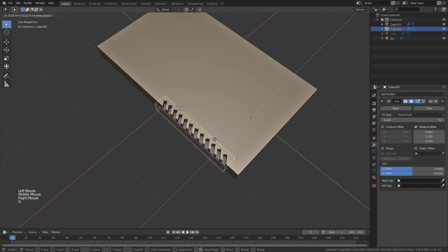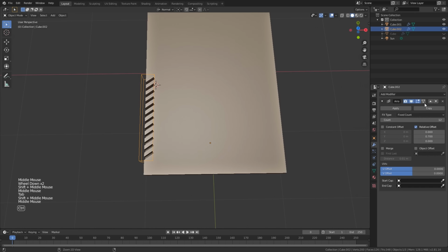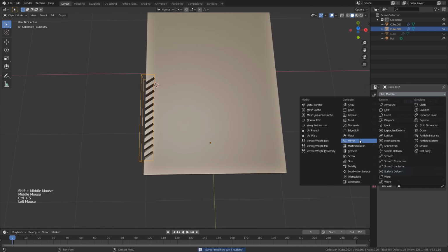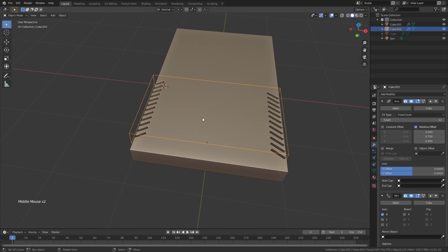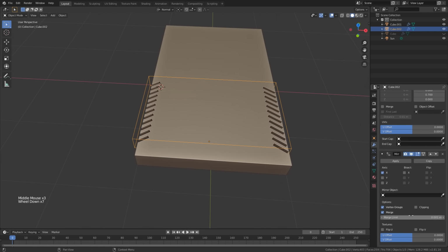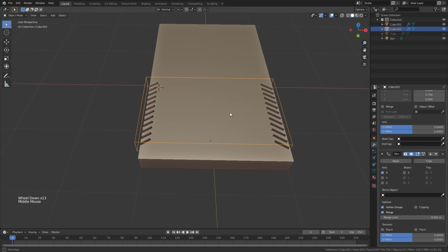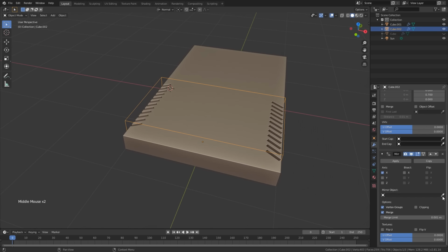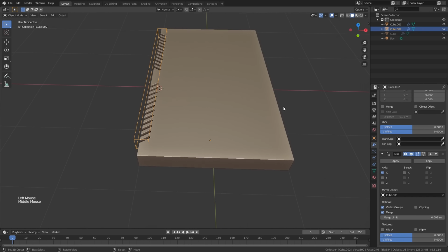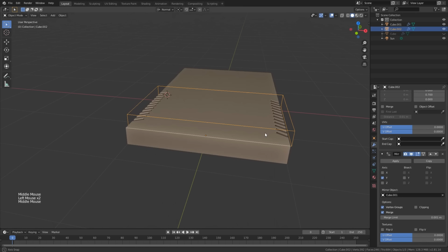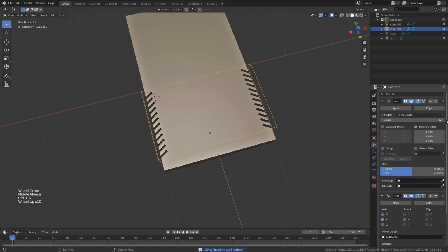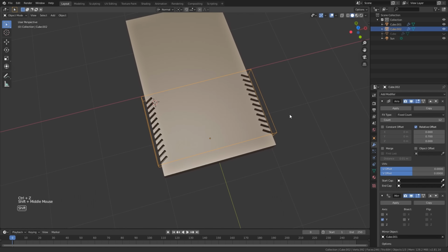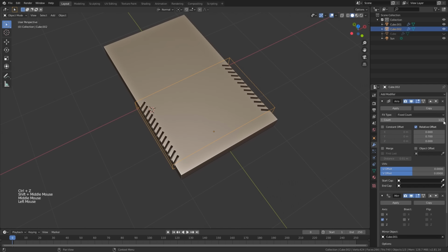Okay, most of it. Now one more interesting thing we can do is we can apply a mirror modifier on this, and you can see the cutouts are happening on both sides now. Okay, now for this to align, for this to pick up the center, I can choose this object, and instead of X I'll try Y. Now I have cutouts on both sides. Now if I increase the numbers,